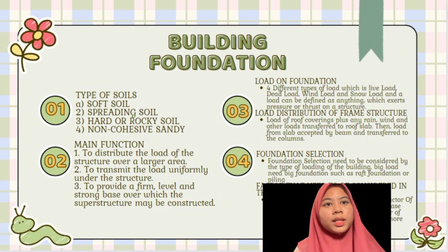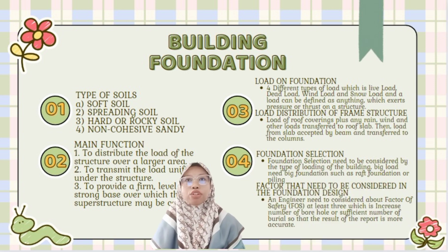Next is what is the main function of building foundation. The first one is to distribute the load of the structure over a large area, and the second one is to transmit the load uniformly under the structure. Last but not least is to provide a firm, level and strong base over which the superstructure may be constructed. So that is all from me. Thank you.